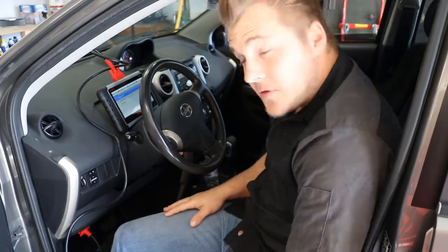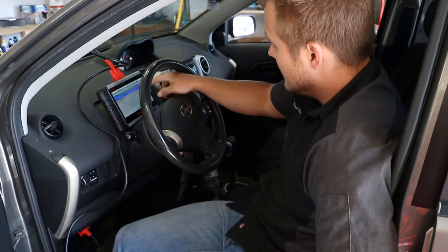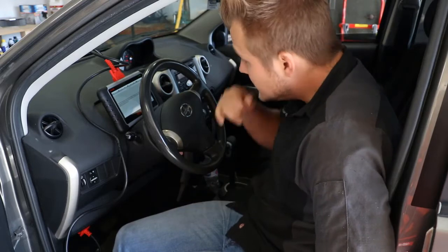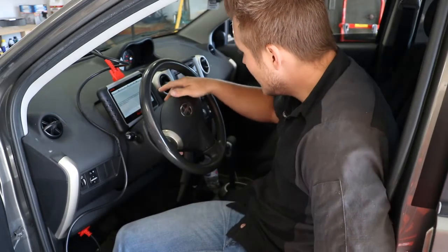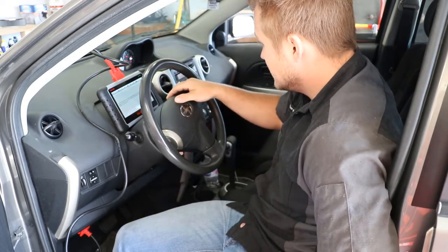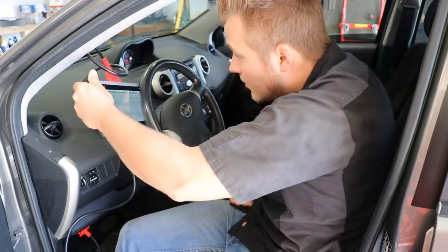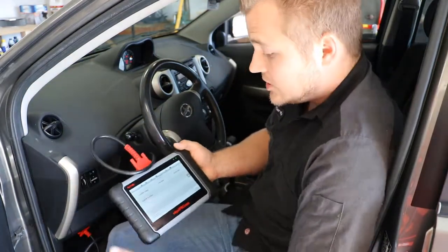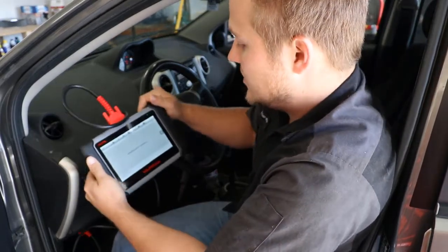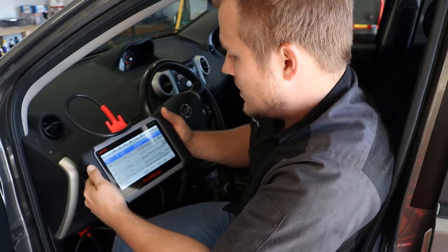Alright, so we're done here with all of the systems. We're going to go ahead and select our engine code here and see what our 9 ones are. The ECU controls the fuel injection, knock, speed, self-diagnosis function, backup function for extraordinary circumstances, and running emissions. Okay, continuing. Alright, so now we got to our engine ECU. We're going to check our trouble codes here. I know it's kind of hard to see through the camera, but we are going to pull these up here.